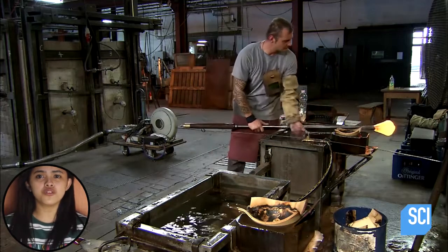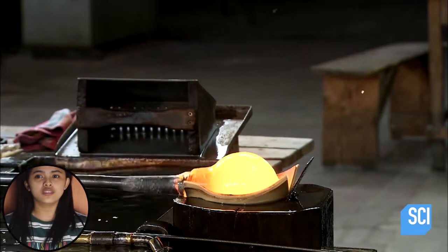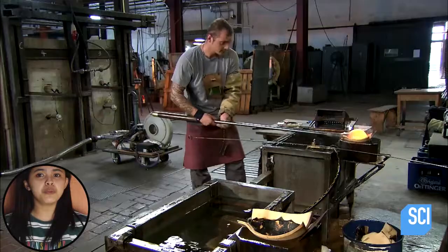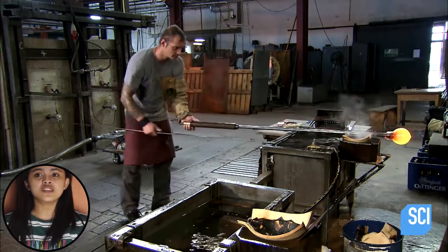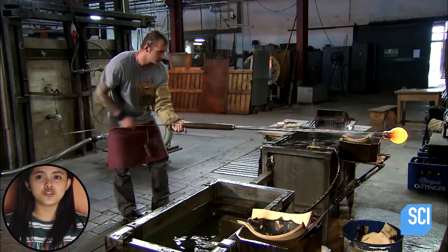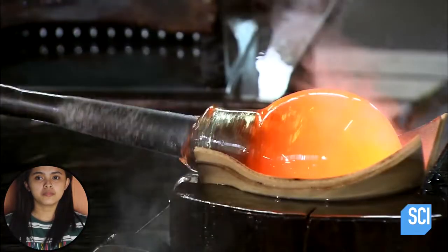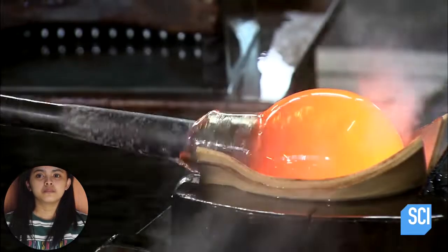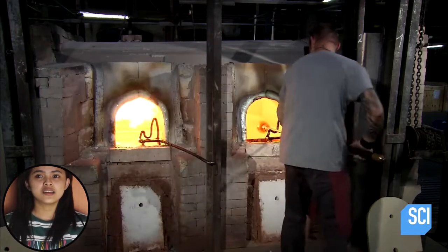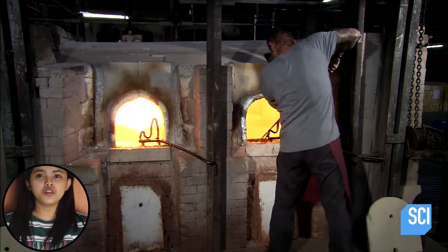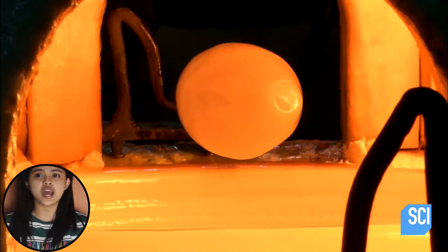He takes a small amount of colorless molten glass out of the furnace and rotates it in a wood mold. The mold is lined with heavy paper to soften the surface. Then, he inserts a metal needle through the blowpipe to create a pathway for air. He returns to the furnace for more molten glass. The artisans make multiple trips to the furnace, shaping the molten glass in stages so it's easier to handle.